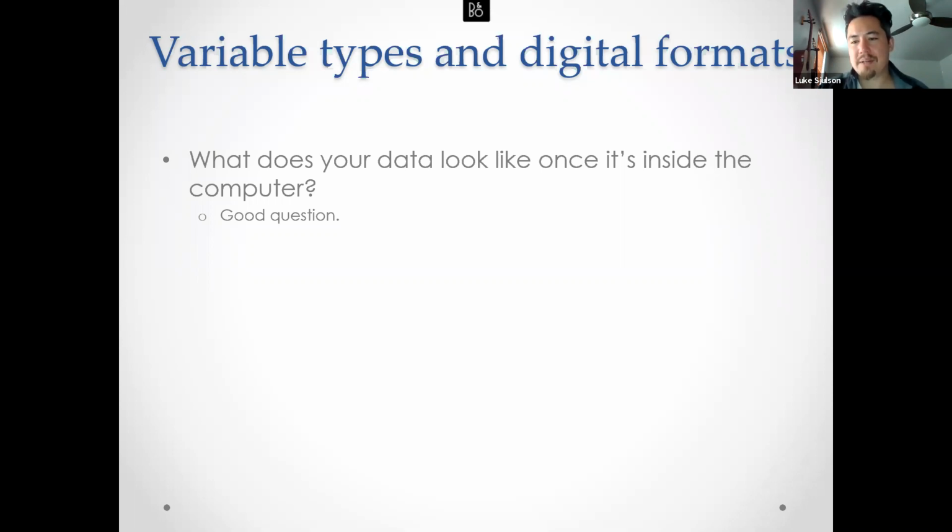We'll have to synchronize our electrophysiology, our video, our behavior, and this microphone, because they're all in different systems with different sampling rates. Behavior maybe is another example where you can use a 30 hertz camera, because the position of an animal's body does not change on millisecond time scales. It changes on maybe tens of milliseconds time scales. So I guess the key answer is that you have to know what it is you're trying to measure first and what you expect to see, and base it on that. Okay, thanks.